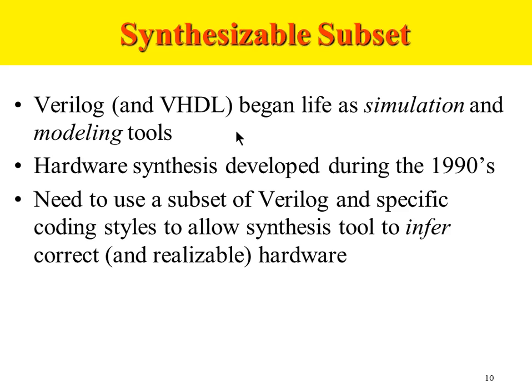Verilog and even VHDL began their life as hardware languages, as simulation tools and modeling tools, back in the early 1990s. Then hardware synthesis was developed during the second half of the 1990s. Synthesis is a concept which converts Verilog and VHDL code into a gate level netlist, which can then be used for design purposes. So we have to use a subset of Verilog and specific coding styles to allow synthesis to infer correct and realizable hardware.